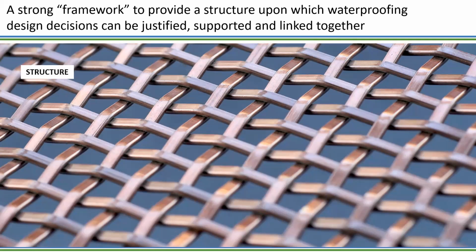Okay, so we've got in situ reinforced concrete, precast concrete panels. We've got sheet piles, contiguous secant piles. We've got ground beams, raft slabs, strip footings. We've got all these components that make a building, and I need to assess how water resistant the structure is in its own right. In some cases, how appropriate it is for the application of certain types of products, okay, which are compatible with different structures. So that's the structure. Everything starts with the structure.